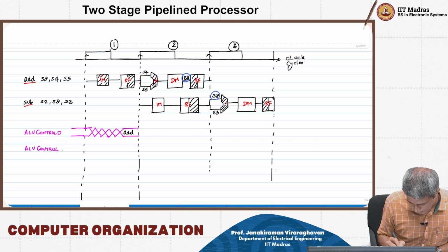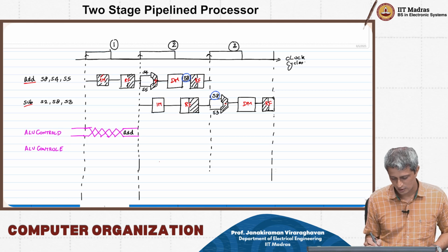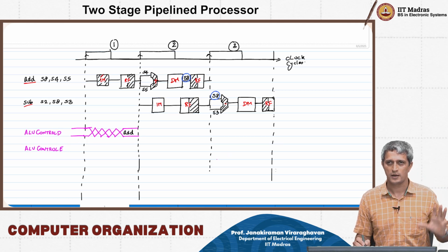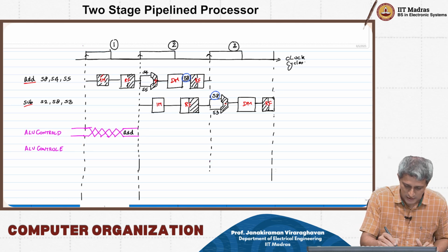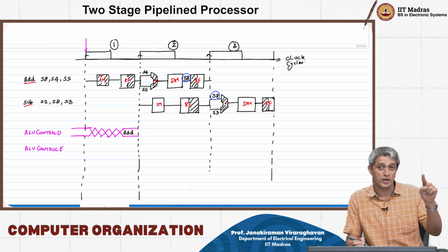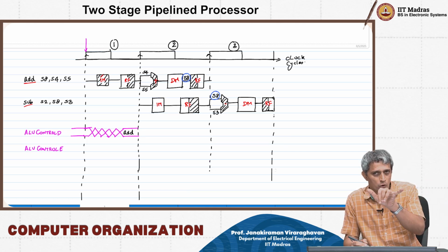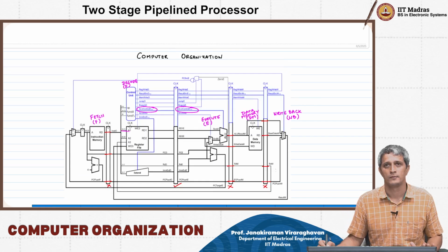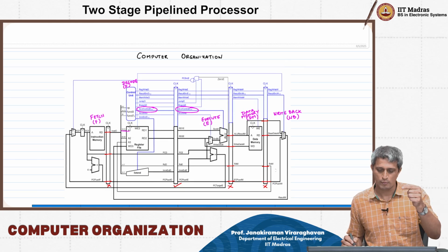So this is D, control E, execute, right? The fact that this is an add instruction, right? At this point, it's the program counter that is launching something. That is still the launch flop, and then we are looking at the capture flop being this intermediate flop after the register file. Okay, so the program counter is where we are starting. Then you go through the data memory and come out.